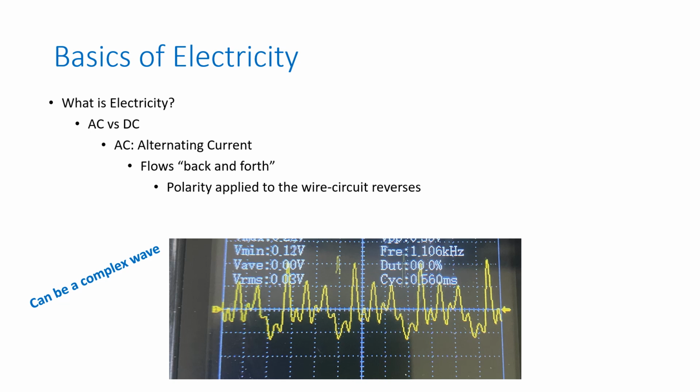It is not a sine wave, as you can tell. It is very far from it. The human voice has a lot of harmonics and subharmonics mixed together. So get used to seeing things like this, but this is not a radio wave, and it won't pass through an RF circuit very well unless it is superimposed on a radio wave. That is an RF frequency signal.